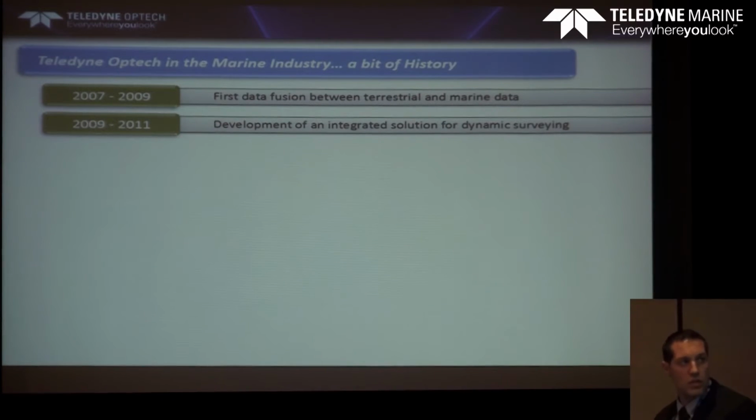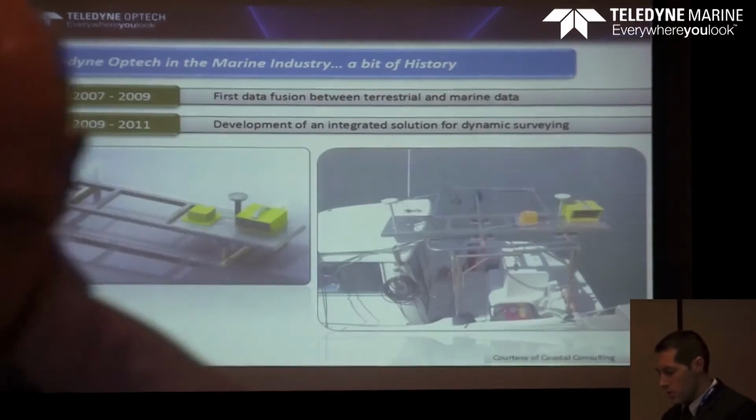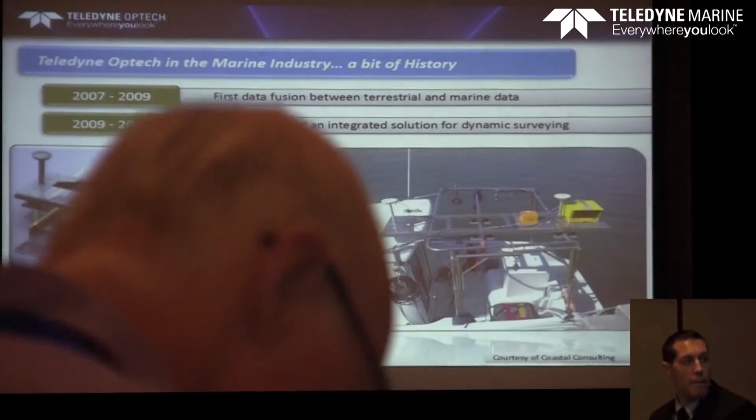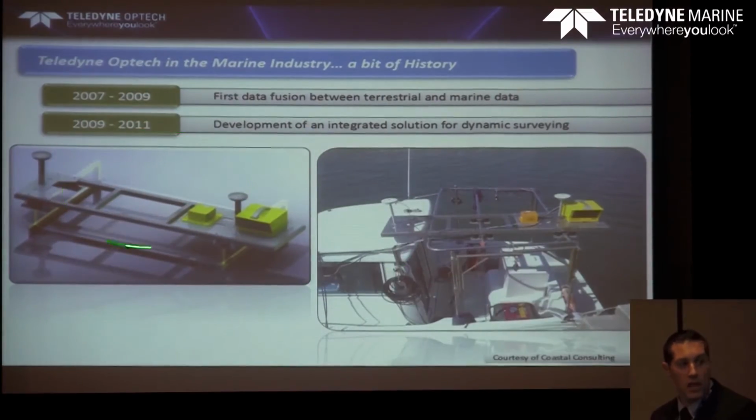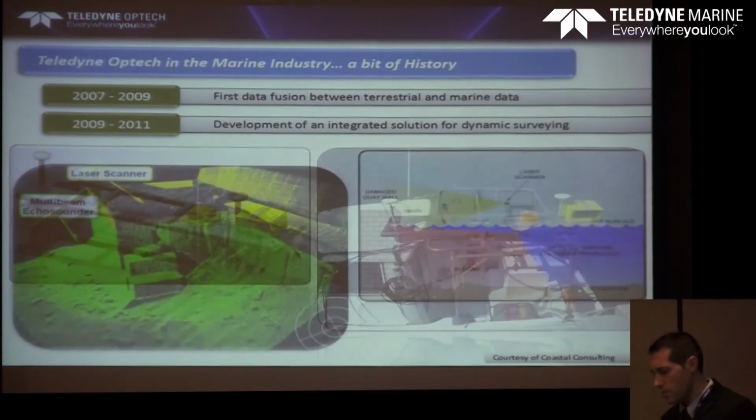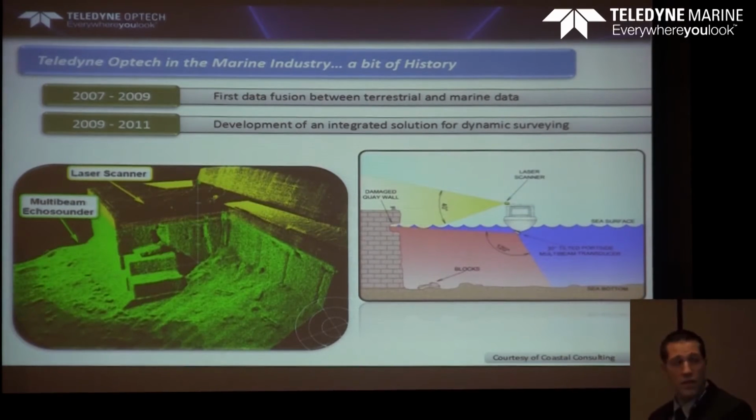at that time, just to start doing the integration between the laser scanner and the bathymetry system. So we came out with this, which is actually our platform. You have your laser scanner, and next to the laser scanner the inertial system, and two GNSS antennas. Basically you put this on the boat, of course you run the calibration, and boom, you're ready to go.